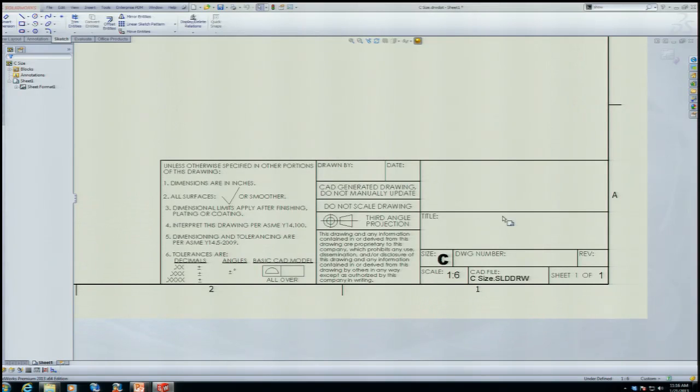All right. So, I mean, there's all kinds of elements you can put into a drawing template. These are the choices I had from a previous incarnation of my life, and I would basically declare what your unit of measure is. You can try to throw in surface finish, the ANSI standards, have your little disclaimer, third angle projection. So basically, go through and add all of these individual annotations into your title block.